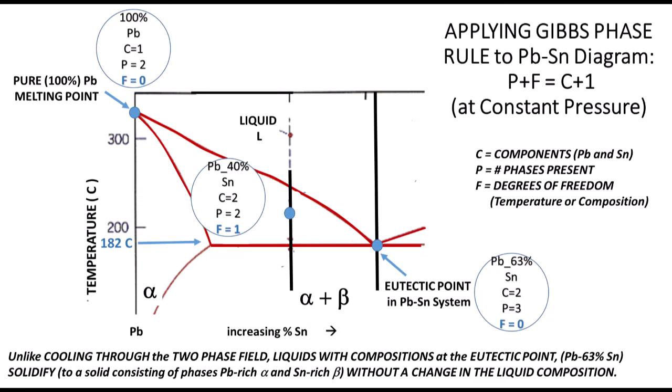The left red curve of that two-phase region. The liquid follows the liquidus curve, sliding down from the liquidus temperature down to the right towards the eutectic temperature. So the liquid is becoming enriched in tin as it cools. Eventually, that liquid will reach that eutectic temperature at the eutectic composition, and that remaining liquid will then transform to the alpha and beta of the two-phase region.